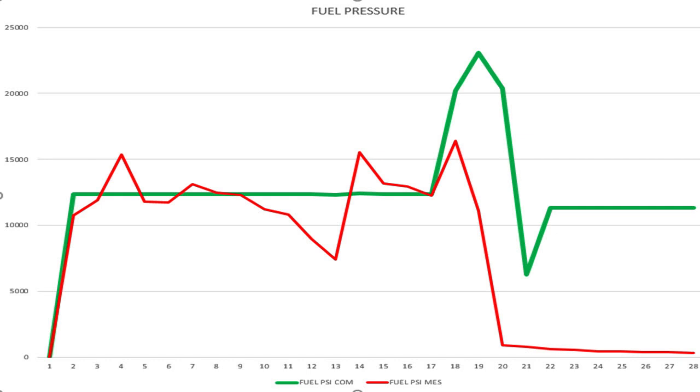So the engineers know that if you get a little bit of air in the fuel or high fuel restriction, you can have these red spikes, or the fuel pressure spikes above the commanded. Then when you go to put a heavy load on the engine, the fuel pressure commanded jumps up to the 20, 30,000 range, so that you've got fuel for horsepower, and the gallons per hour increases and the milligrams per stroke increases, and it's just not there through the pressure tanks.